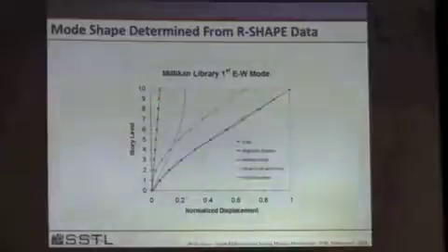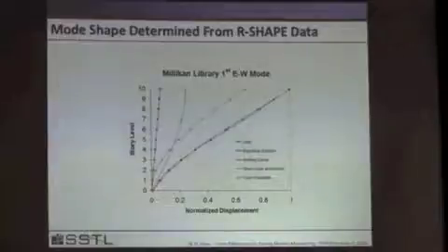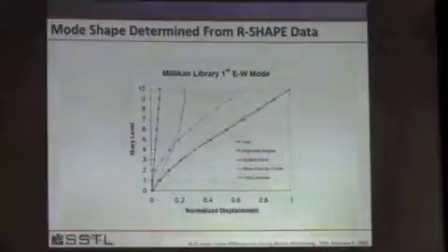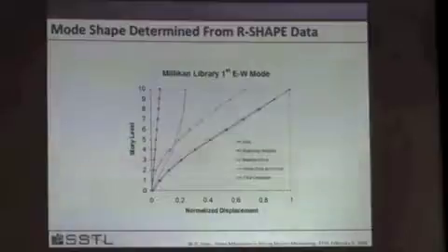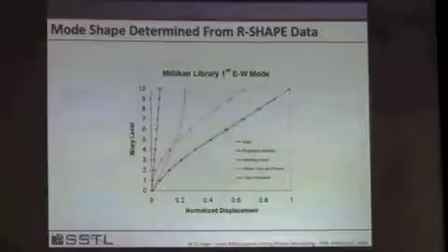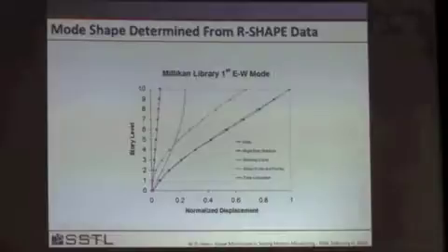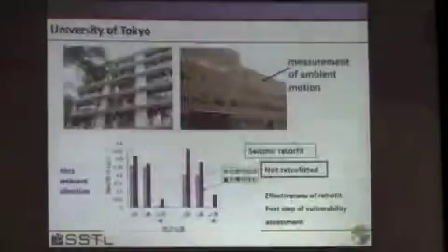First of all, this is the rigid body rotation of the building on its foundation. This blue line is the shear of the core and the frame, and then the yellow line is the bending of the core. So in contrast to what we typically assume for the behavior of a 10-story building, which is dominated by shear, you had a combination of bending, shear, and rigid body rotation that were all needed to understand how that building responds. Is that followed in torsion, right?